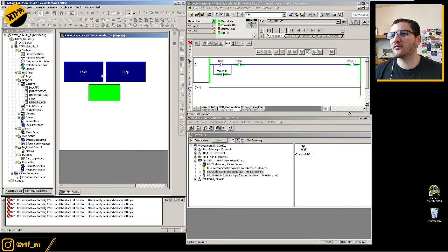That's all for today's video, folks. Chapter 8, Chapter 7, we covered both chapters. They both are on how to connect your emulated controller. In real life, it's very similar. Your physical controller is going to sit in the same location within RSLinx Classic. You can use either RSLinx Enterprise or OPC directly. They're both OPC, which is just the method that is slightly different, all right?